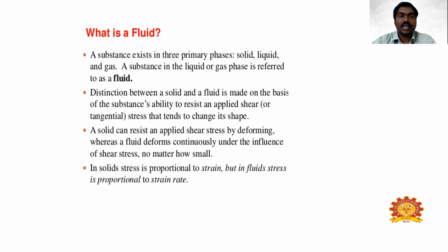A solid can resist an applied shear stress by deforming, whereas a fluid deforms continuously under the influence of shear stress, no matter how small. In a solid, stress is proportional to strain, but in a fluid, stress is proportional to the strain rate.